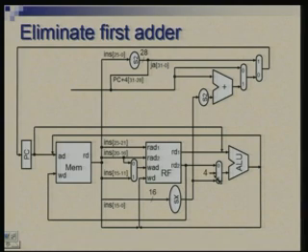The output of this adder which was here was eventually going through this multiplexer to be stored back into PC. So, that we will have to tap from this point now. So, we remove that connection from top and take a connection from here.